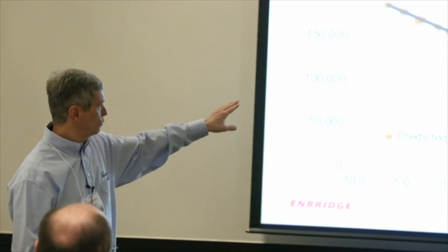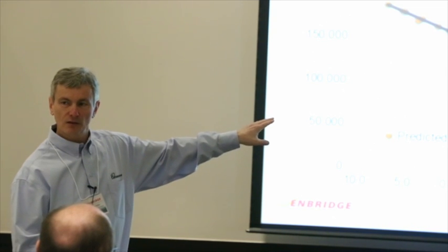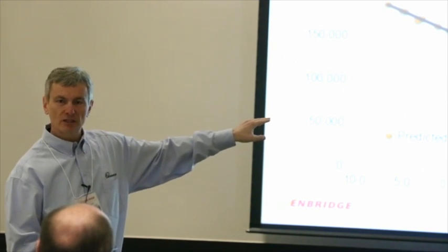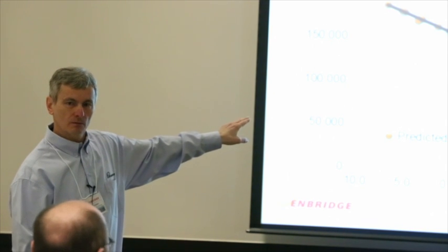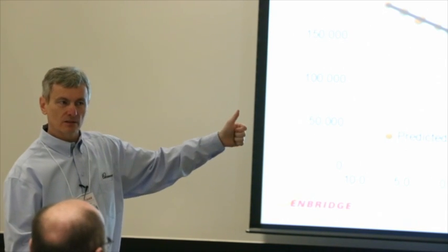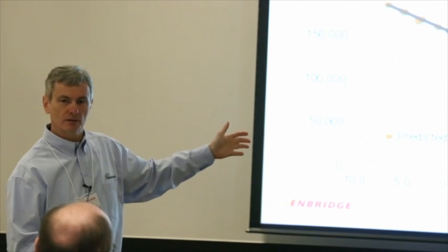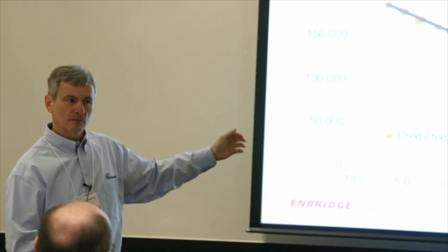The way I look at R square, 0.87, that tells me that 13% of the energy that I use is not explained by these two factors. And if I know that I don't use energy for anything else but seasonal and production, that means that I have 13% waste in my system. That's all you have to look at.